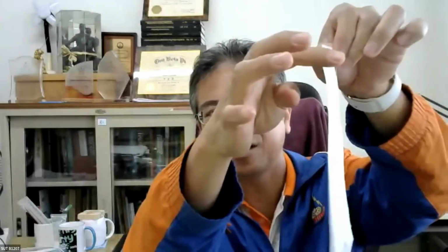Let me stop sharing for a little bit and show you guys about this connection. This is the ABC. The bolt on the top is bigger than the bolt on the bottom. The problem said the top portion AB has only one plate, 9 millimeter thick. The bottom has two plates, each 6 millimeter thick. And this plate is connected to a bolt at A, just a bolt at A.